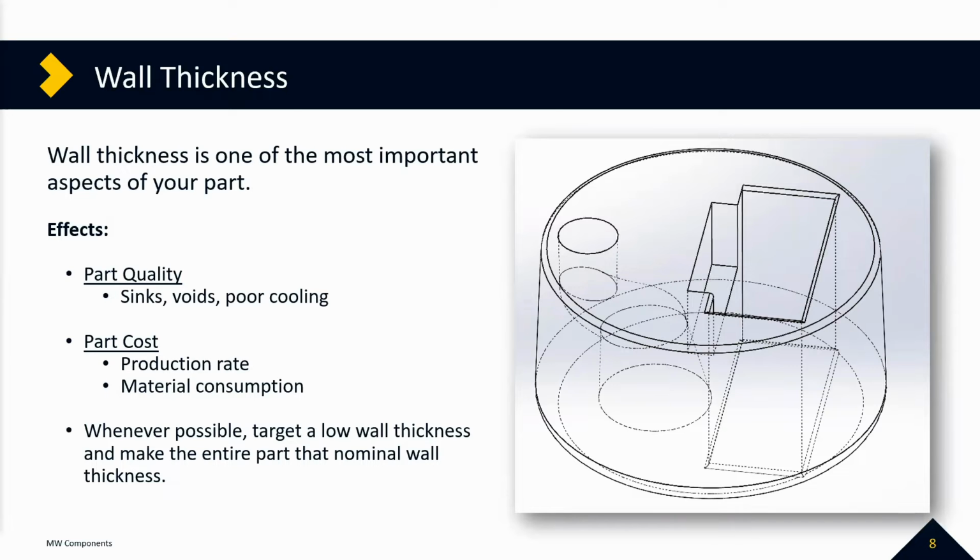You want to get rid of big chunky areas of your part, because they are going to cool much less reliably than the thinner sections, and much slower, because of how much plastic likes to retain heat during the molding process. There's a reason it's an insulator and you're putting it in a heat conductive steel frame, or mold rather.